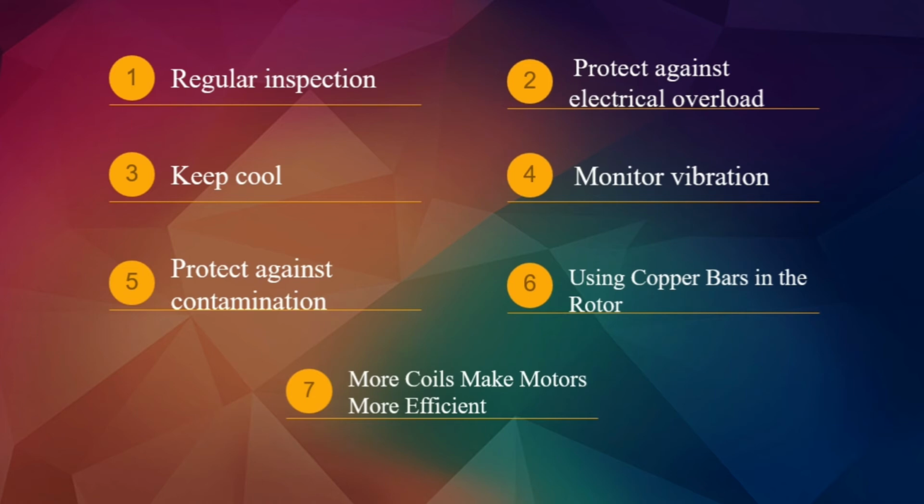Vibration in electric motor is commonly caused by an uneven or unstable surface. However, it can also be a result of underlying problems such as loose bearing, corrosion, or misalignment. It's important to monitor vibration level as excess vibration can cause the motor to fail prematurely.